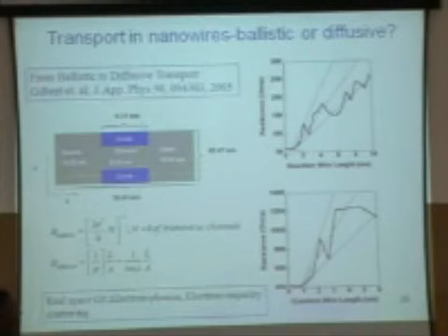So if your channels are 2, 3 nanometers, and maybe, of course, this way is very long, so it's not necessarily, most likely for practical use, we are not in the so-called ballistic regime, but rather in the diffusive regime. So we have to do diffusive calculations.